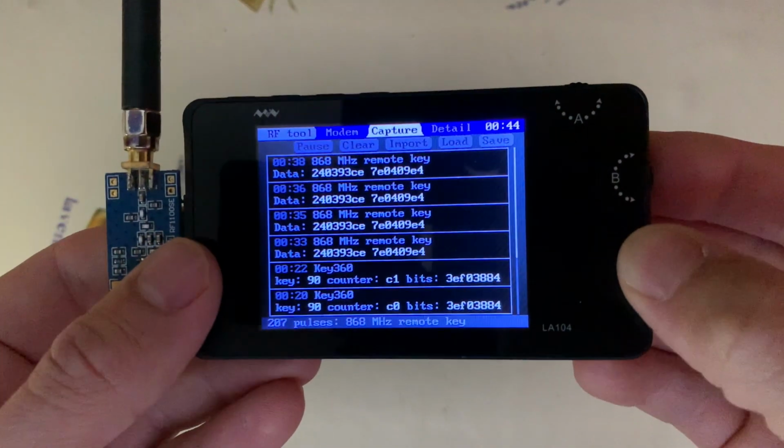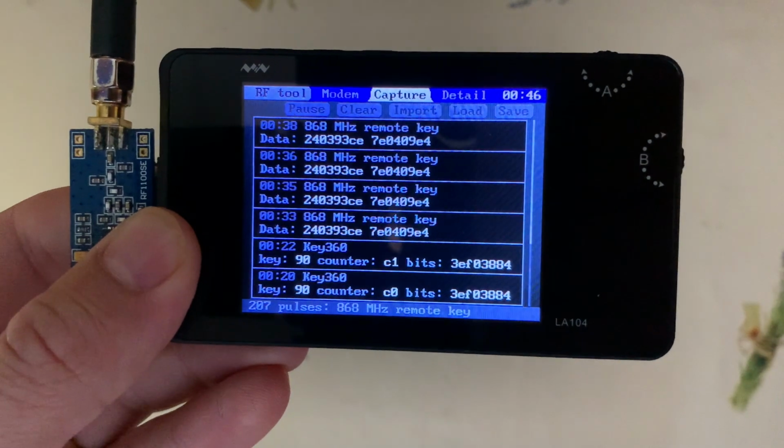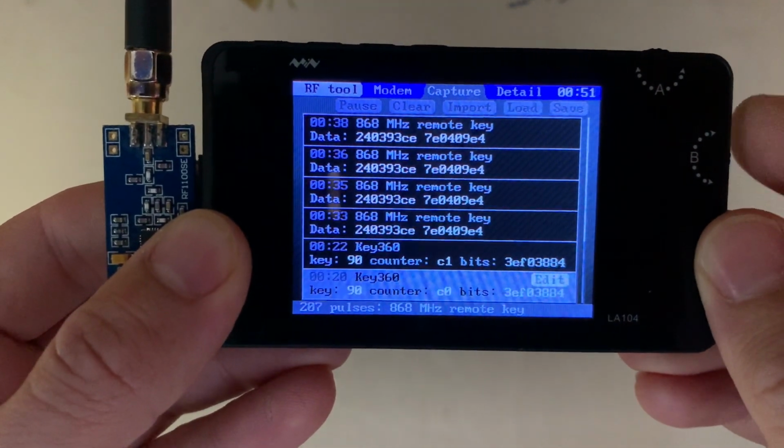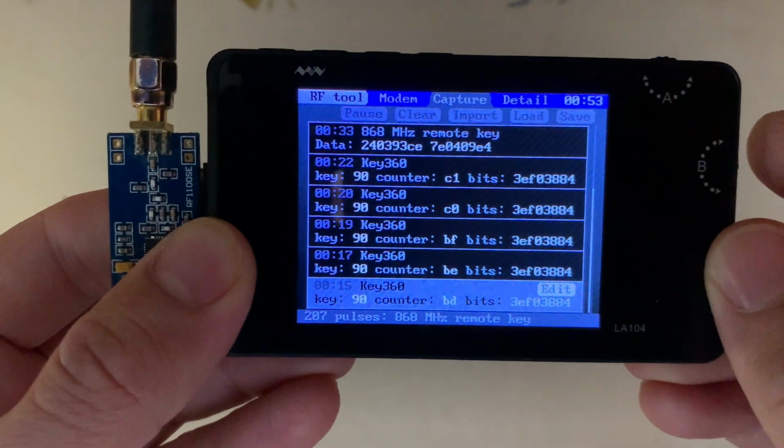We can see that the last 4 codes are completely the same with the length of 64 bits. And the only variable part of the other codes is 8-bit incrementing counter, which is very easy to hack.